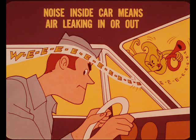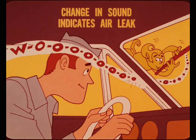In most cases, you can identify an air leak noise by opening the fresh air inlet doors so ram air can build up pressure in the car body. As air pressure inside the car body varies, a change in the noise sound indicates that the cause is an air leak, probably at some poor contact point on the weather strip or a leaky vent wing seal.